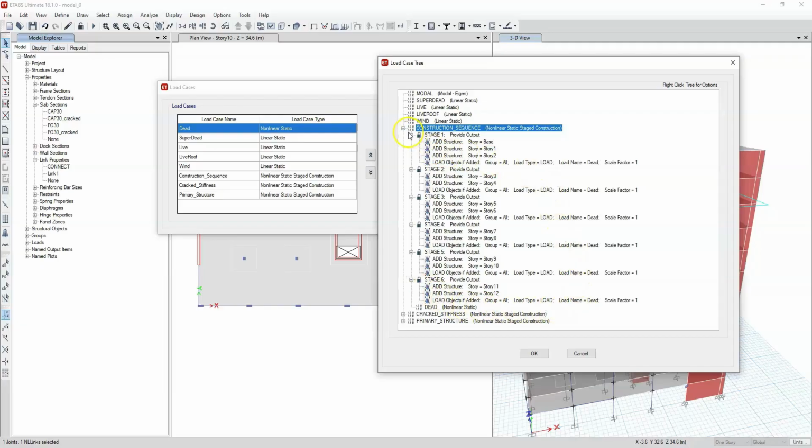The results of the staged construction process, building a model with, for example, 2 floors at a time, allow us to have results at the end of the model without spurious deformations that are unnecessary and that also produce spurious internal forces. Normally, we counteract this with larger effective areas for the columns, but we can do it directly in the application with a staged construction tool.